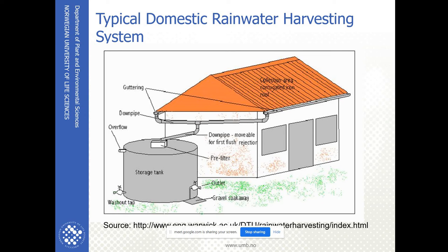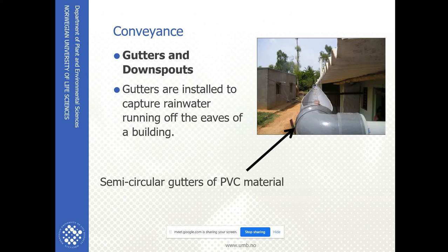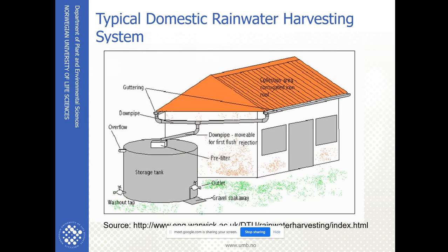In case of difficulties in the rejection of the first flow, clean the roof and gutter at the beginning of the rainy season. Method to enhance quality: cleanliness of the roof and storage tank is critical in maintaining good quality of rainwater. The storage tank requires cleaning, and this is significant when the tank is empty, at least once in a year.